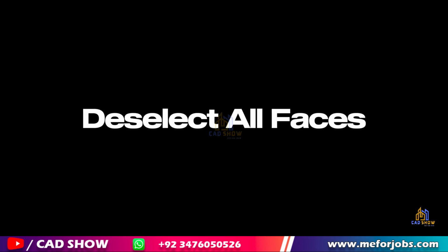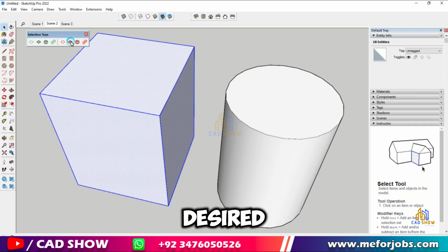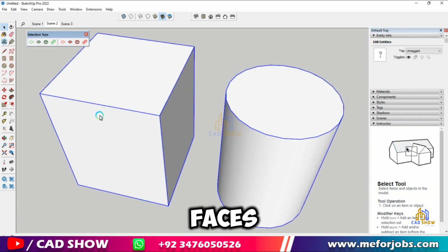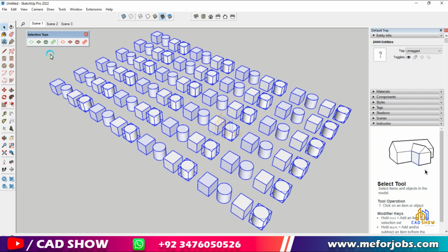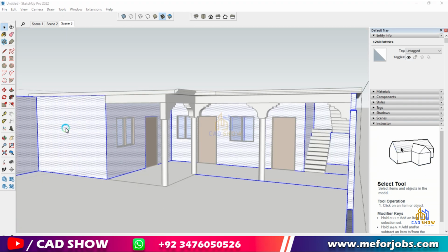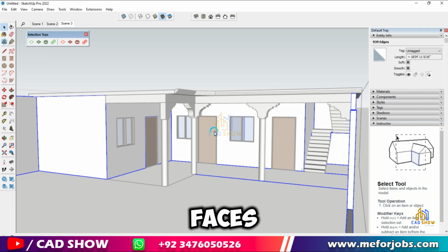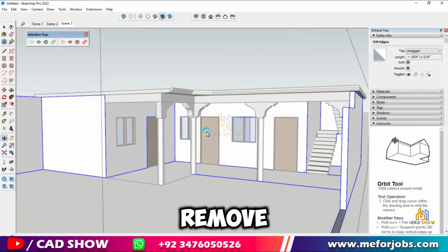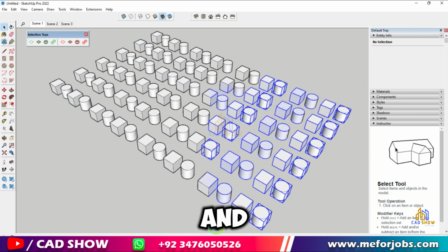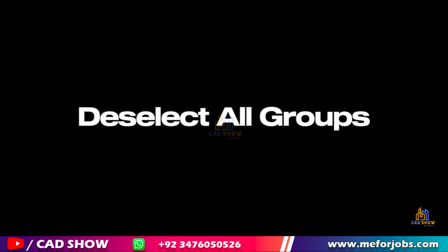Number 6. Deselect All Faces. Select your desired area. Click the Deselect All Faces icon, and all faces will be removed from the selection. This tool is perfect for focusing on the structural elements of your model. The Deselect All Faces in Current Selection tool allows you to remove all faces from your current selection, leaving only edges, groups, and components.